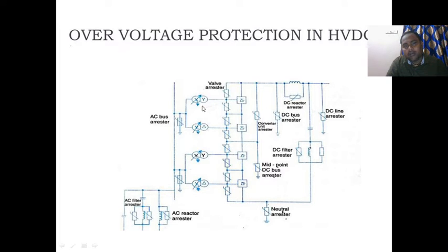The combined operation of two 6 pulse converters is a 12 pulse converter unit. The waveform of 12 pulses is present only when the transformers are star to star and star to delta. Then only a phase shift of 30 degrees is possible, then only two 6 pulse waveforms are added, and that gives 12 pulses.